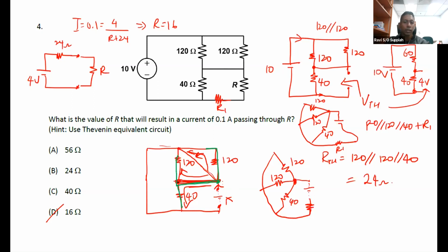All right. So I think the confusion comes because you see a short circuit line here. Yeah, right? Okay, that's why the confusion comes. But you have to imagine that this short circuit line means this point here and this point here are the same. All right, which means that when the current comes here, from this imaginary voltage source, I will have to split. There are three pathways. One is this way, one is this way, and the other is this way. All right, so all three pathways have resistors there, so there is no way to just skip anything.